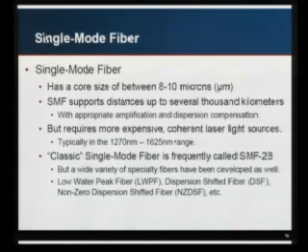It's typically somewhere between 8 to 10 microns. And because of that, single mode supports distances up to several thousand kilometers with appropriate amplification and dispersion compensation, which you'll get more into. The downside, obviously, is that it requires more expensive lasers. They typically operate in the range of 1270 to 1625, and that may vary by a few nanometers here or there, but that's pretty much the bandwidth that's covered by all the lasers.